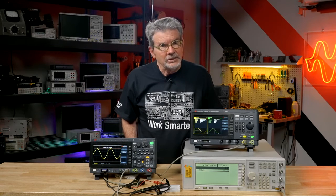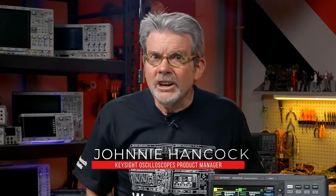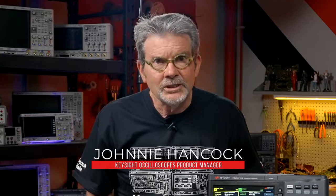In this lesson, we are going to be talking about and demonstrating important oscilloscope specifications that you should be familiar with. Hi, my name is Johnny Hancock, Product Manager for Keysight's InfiniVision oscilloscopes. Oscilloscopes have lots of specifications, but there are a few important ones, including bandwidth, sample rate, vertical resolution, memory depth, and number of channels. But the most important oscilloscope specification is bandwidth.